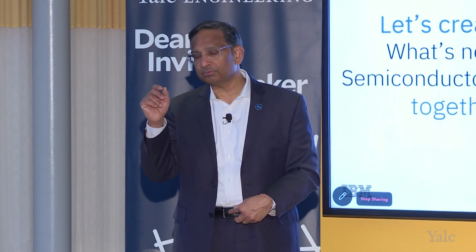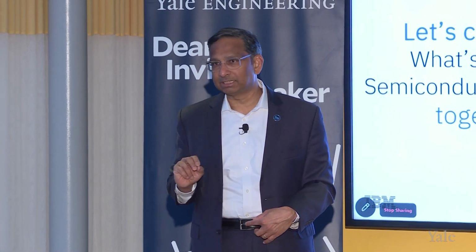But then that is not going to be enough. So it's truly not analog. There's digital around it as well to reduce some of the noise, some of the error, to be able to make it compatible. So it's a journey. I will say the range right now is very big, and it's a longer term project for us to get to a reasonable accuracy. And I showed you the number of individual synaptic elements was not too many. It's only 16 meg basically, which is very small. If you look at the size of models these days, they are 2 or 3 orders of magnitude bigger. So we have to look at smaller models and a certain class of applications which can be used for this type of analog AI chip, and that's why we are describing it more towards edge and relatively smaller models that can be deployed right now.